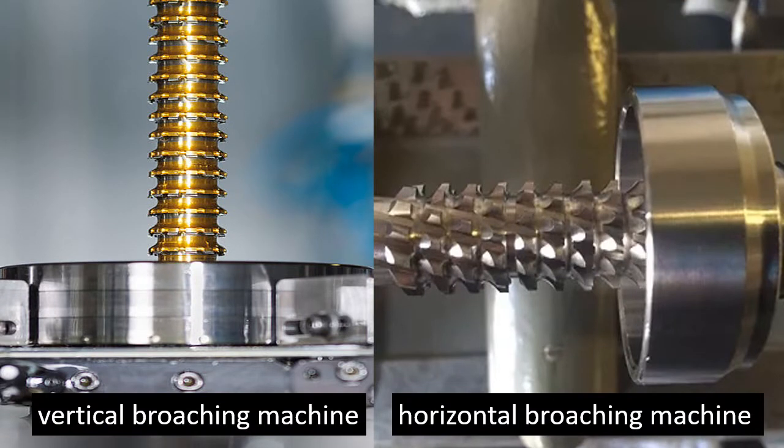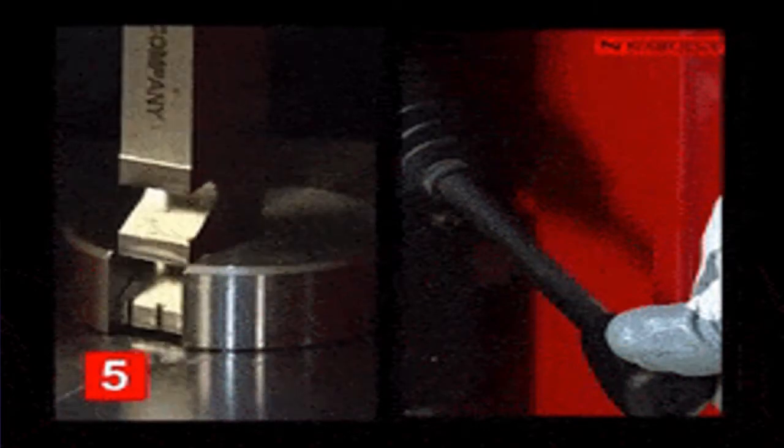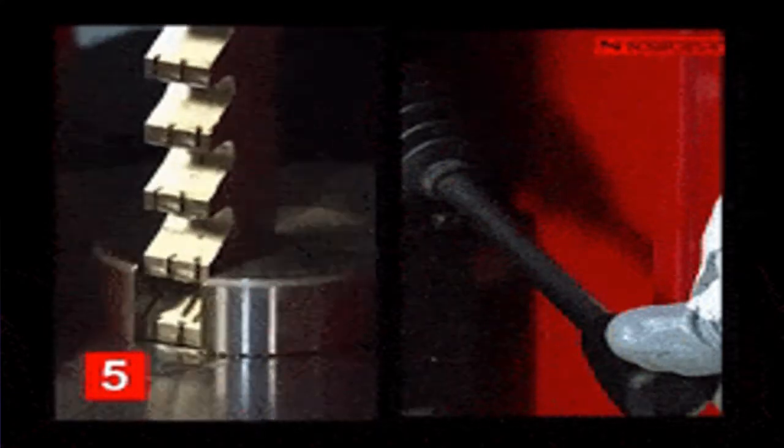Broaching machines can be classified into vertical and horizontal broaching machines. The vertical broaching machine is designed to move the broach along a vertical path, while the horizontal broaching machine has a horizontal tool path. Broaching also can be classified into internal and external broaching. Broaching presses, used only for internal broaching, push the tool through the work part.